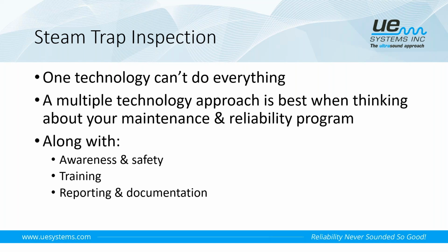Also, in your plants and facilities, we want to try to create awareness and safety. One way to create awareness of how we need to be more mindful and better maintain our steam system is by putting a dollar amount to it, showing how much energy waste can be associated with failed or leaking steam traps. If you're in a plant where there's some excessive high pressure steam in use, then that becomes a safety issue.